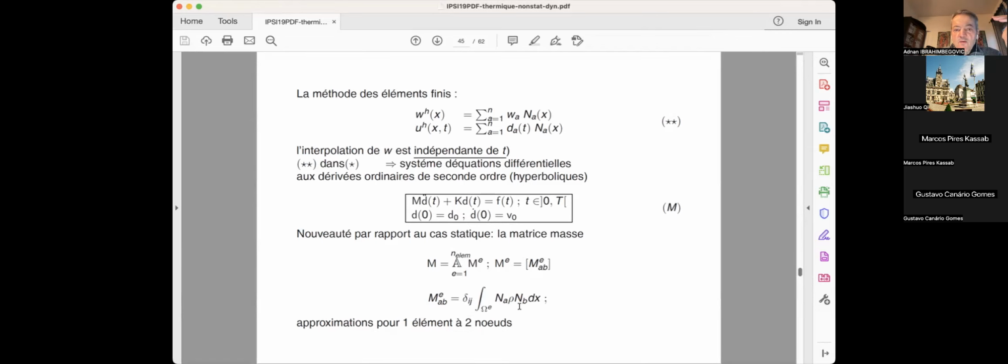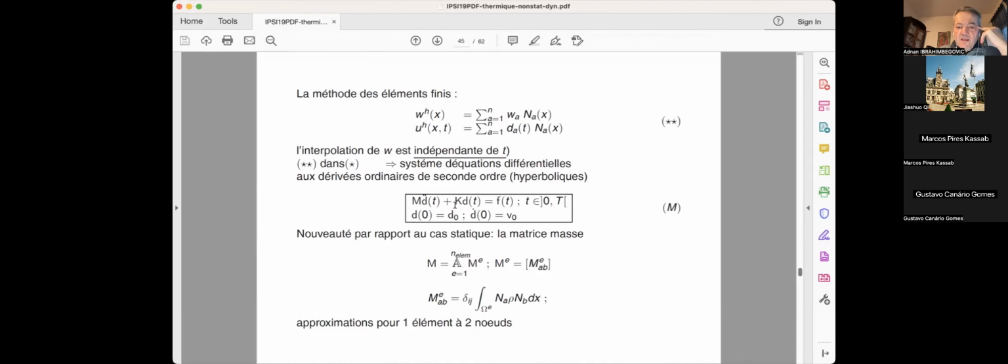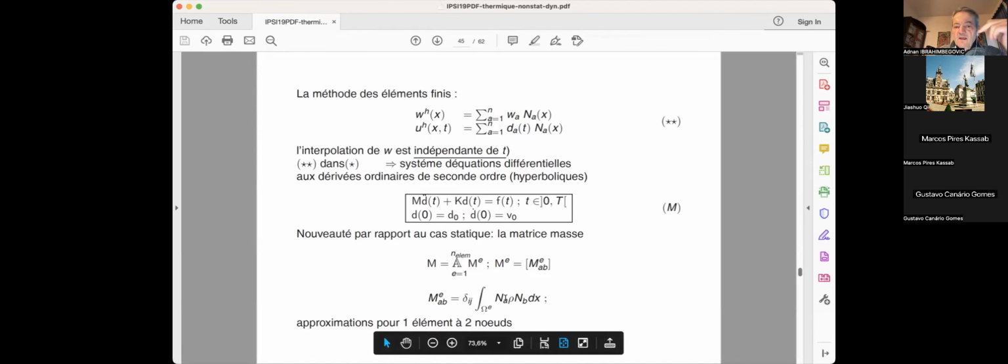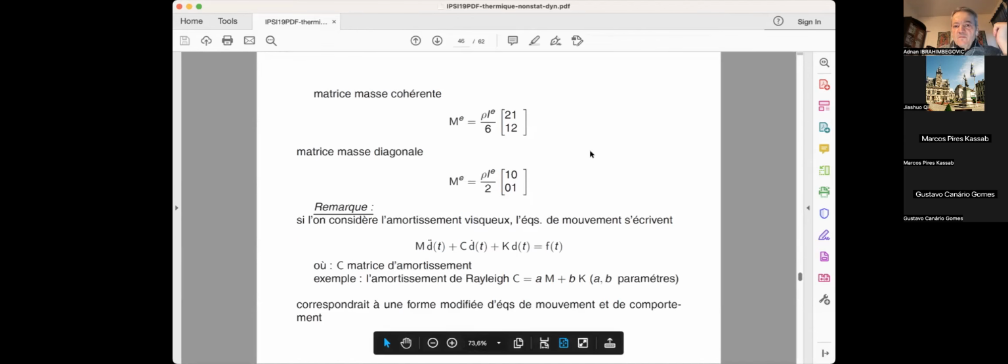So if I have a two-node truss bar element, recall for computing stiffness matrix, internal forces and stuff like that, it's typically enough to have one Gauss point. Obviously, if I have a mass matrix, given that these functions for the two-node truss bar element are linear polynomials, linear times linear builds me a quadratic polynomial. And we could see that one-point Gauss integration can only integrate exactly a linear polynomial. So you have to upgrade, you have to go to two-point integration to get the mass correctly. If you do that, or you can integrate it directly, it's not that complicated.